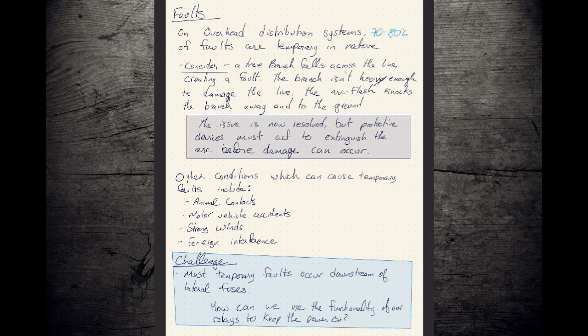You think about a squirrel scrambling up a transformer and it goes phase to ground because it's stretched a little too far across the bushing and poof, no more squirrel. That squirrel can't hurt our distribution system. It could chew on our wires as long as it wanted. It couldn't hurt our distribution system. But what it can do is create an arc. And we already discussed how damaging those arcs can be.